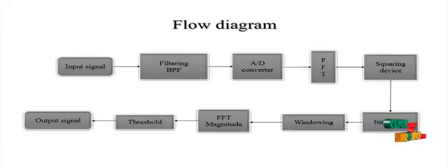So the periodic DFT even forms have only non-zero DFT coefficients and share the benefits of sparse frequency domain representation, with higher generality of the process. So finally we calculate the probability of detection, the probability of false alarm, and the power spectral density of the signal, that is the periodogram, then the Welch power spectral plot, that is calculating the Hamming window, and also the bit error rate. The bit error rate should be reduced compared to the existing one.